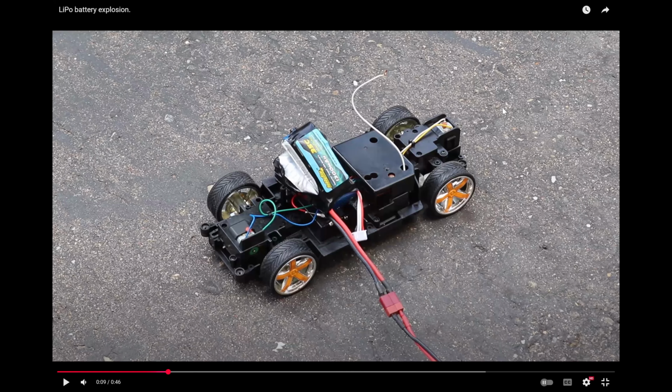That's all I can say. And there's lots and lots of stories of people with drones, especially drones that charge their batteries unattended. They aren't home, and they come home, and their entire house is burning. So the other thing is, it would be very wise to leave a buffer zone around it so that there's not flammable materials very near it. So in case the battery goes on fire, the fire doesn't immediately spread to some really flammable materials right around it.